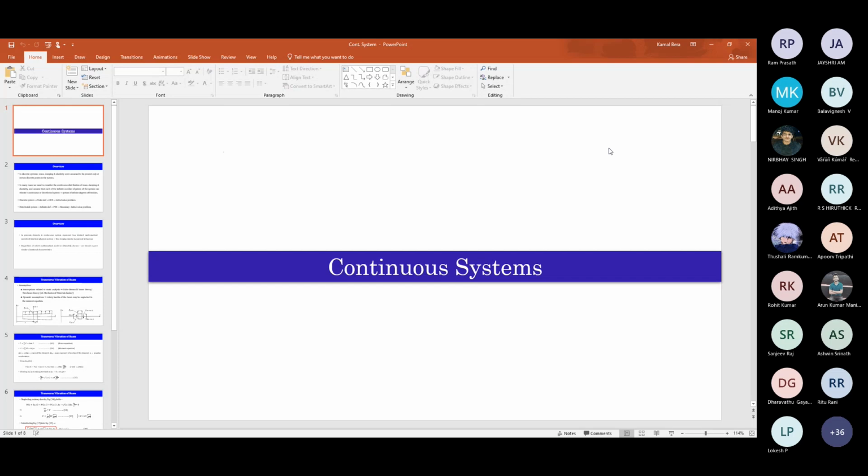We'll just study the simple beam vibration problem here. We'll derive it for a general type of beam, which can have varying EI and varying cross-sectional area, but finally we'll consider a uniform beam and find the natural frequencies and mode shapes. Then first I will validate the orthogonality of the mode shapes.